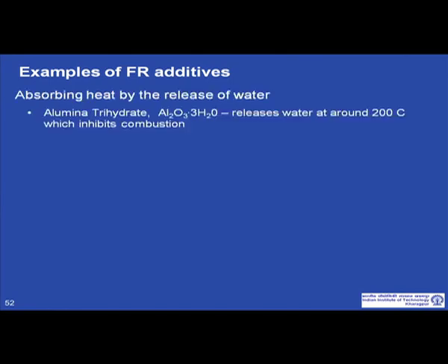So, this was the basis of choosing or designing fire retardants. Now we talk about a few additives which work by one of these mechanisms. For example, alumina trihydrate, in a fire situation, releases water at around 200 degrees centigrade, which inhibits the combustion process. So that is one example of an FR additive which acts as a fire retardant by absorbing heat and releasing water.